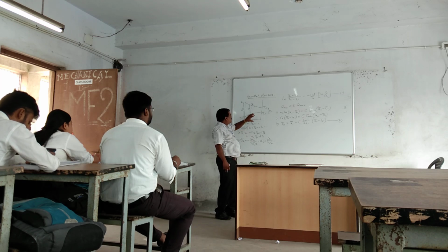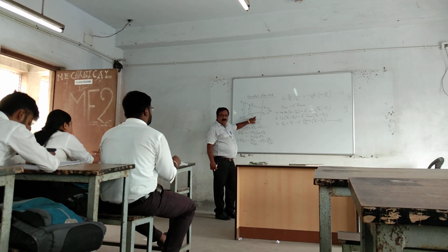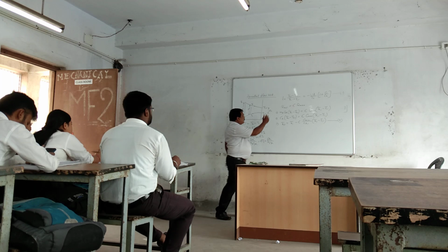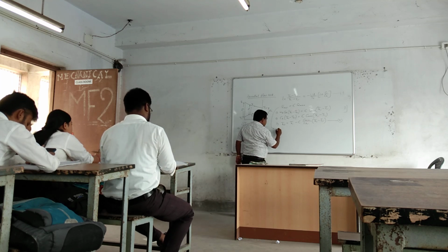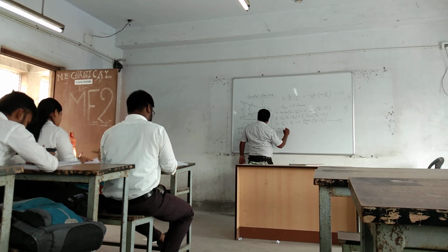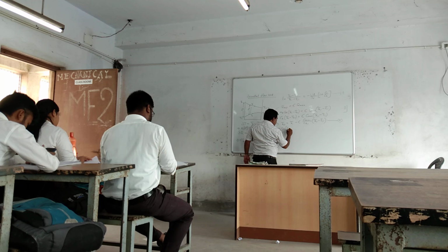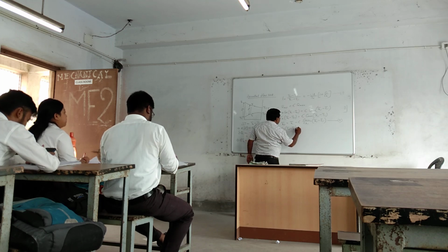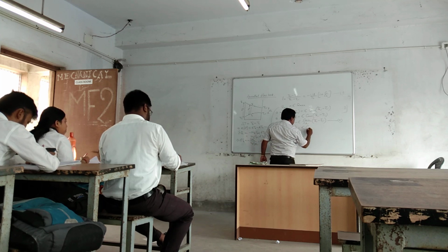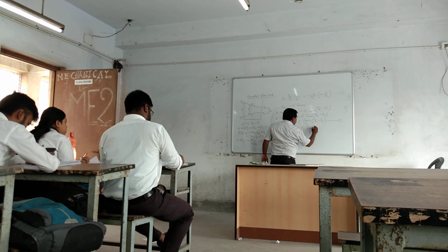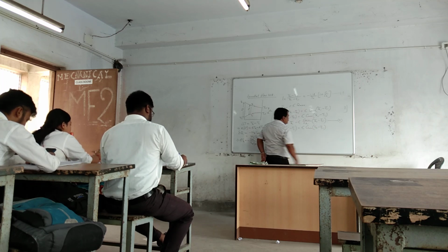What is the Q actual for the cold fluid? That is MC CPC (TCO minus TCI), that is equal to epsilon C minimum (THI minus TCI).